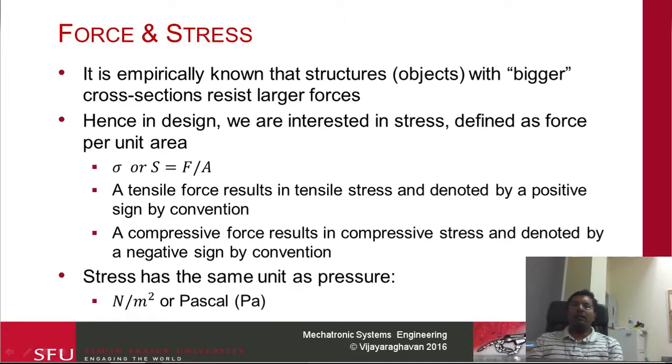When you apply a tensile force, which is basically pulling on the object, the stress that's developed is known as a tensile stress. That makes it thinner and it tries to fall apart. When you squish the object down, essentially compressing it, what we are applying is a compressive force, and it results in a compressive stress. The stress has the same unit as pressure, Newton per meter squared, or Pascal.